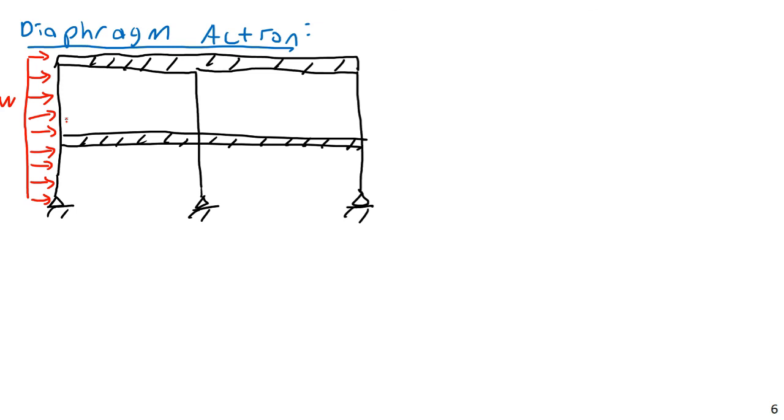As I mentioned previously, the cladding is going to distribute the lateral load. Most of your lateral loads, like wind, are applied not at a point but over an area. Wind is a pressure force. The first element of the building that's going to experience this lateral load, I don't know if you'd call it a structural element, though I suppose you could in certain contexts, is going to be the veneer or the facade, the cladding, whether it's brick, vinyl siding, wood, glass, or whatever the outside of the walls of the building are made of at any given point. They're going to be the first thing that experiences lateral loading. Of course, the cladding is not designed to resist substantial lateral load itself. If you imagine the windows on a 10-story building, imagine if you just removed all the structure behind them and stacked the window panels up in a big tower by themselves and maybe welded them together or something.